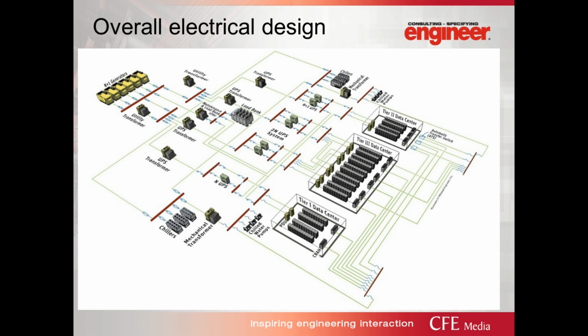And in 5 years from now, it's time to add those next 2 gen sets. The controller technology has upgraded since then. Will that jive with the older generation? Are the owners, operators, and tenants willing to let you test and commission that paralleled common generator system on a live site? Oftentimes that's frowned upon, to say the least. So you need to think about what are the ways that I can expand and scale up my system while maintaining operation.